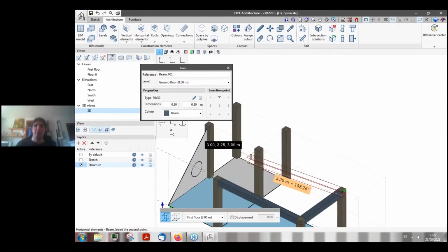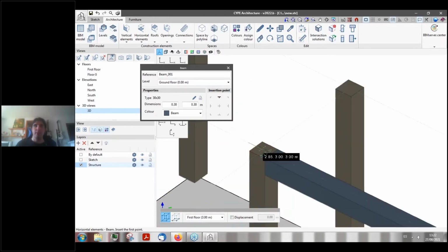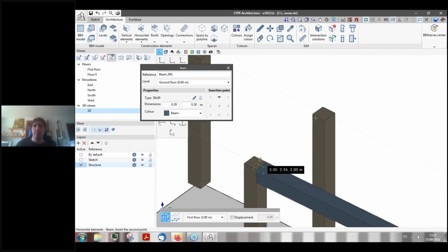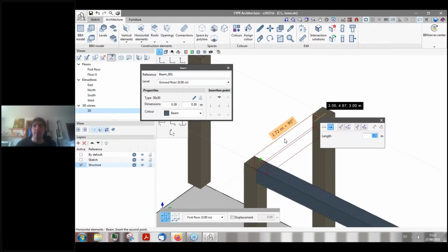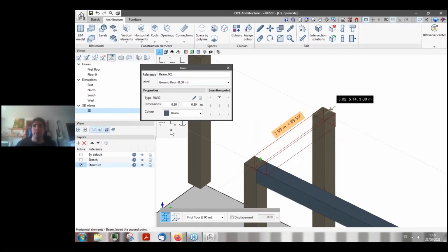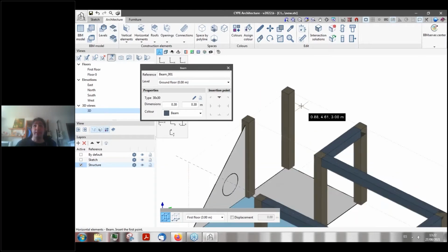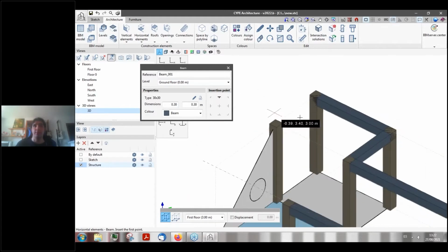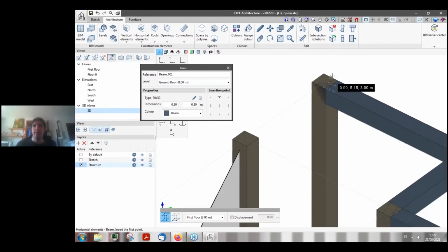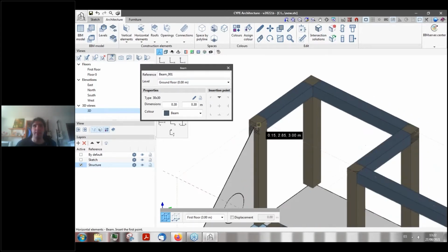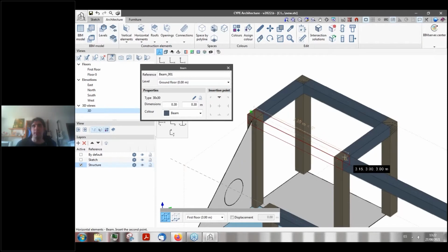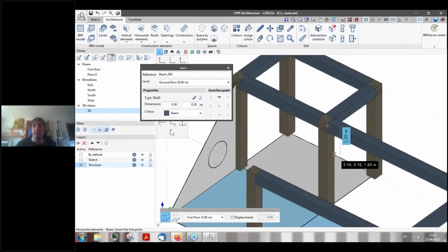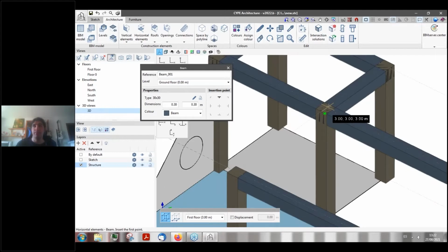Once we have inserted our structural elements, we can switch to the horizontal elements tab, and we can start inserting the different floors that we're going to use. This is where the sketch tab will be most useful, because if you recall correctly, we can use many different kinds of introduction for different elements. In this case, for the beams, what I'm doing is using the default introduction method, that is by points. But later, when we introduce the beams, the slabs, you will see exactly what I'm talking about.